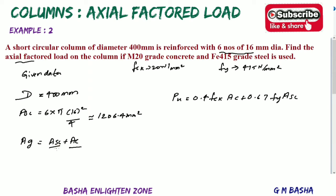Here we already know the area of the steel value, 1206.4. In terms of diameter, the gross area is pi d square by 4, and sending the area of the steel to this side, 1206.4, you will get the Ac value directly. That Ac value will be 124457.3 mm square.